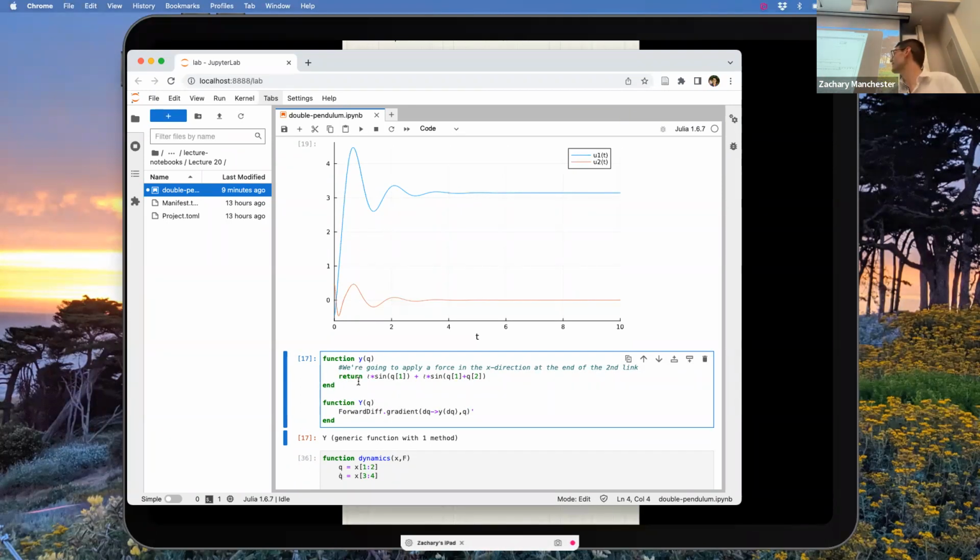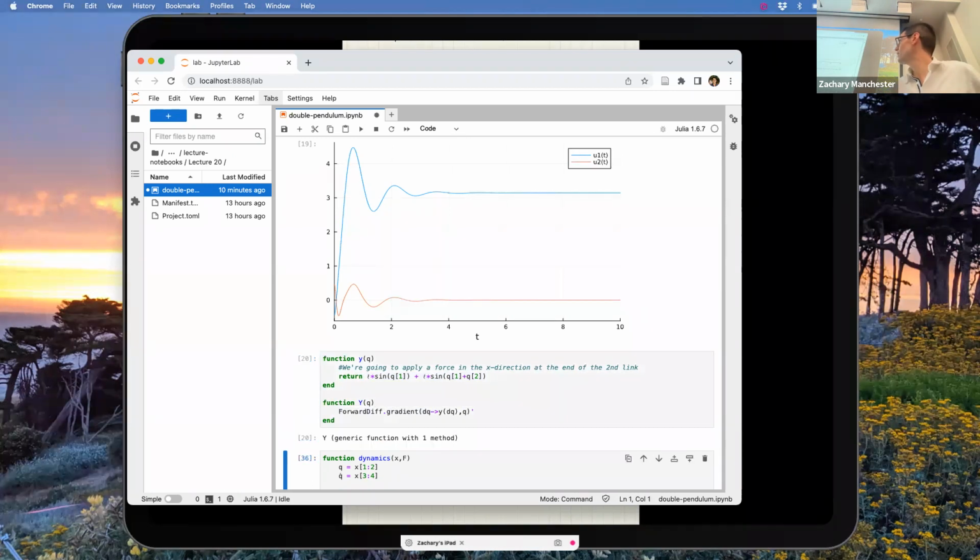What I have to do to get this, so this is the x coordinate of the end of the last link. So I do the forward kinematics down the chain, and I get to the position of the end of the chain, and I take the x coordinate of that, right? That's it. That's what that thing is. And I guess this is the center of mass of that second link, the CG of the second link. So this is part of the forward kinematics that I just basically pulled out, to get me to the point where I'm applying the force in the right direction. I take its Jacobian, and that's the y that we just talked about.